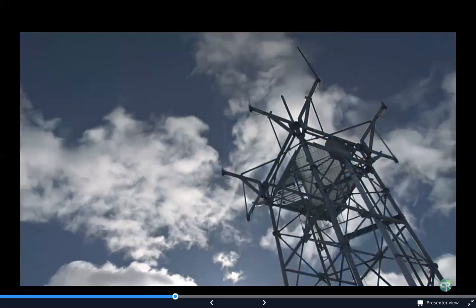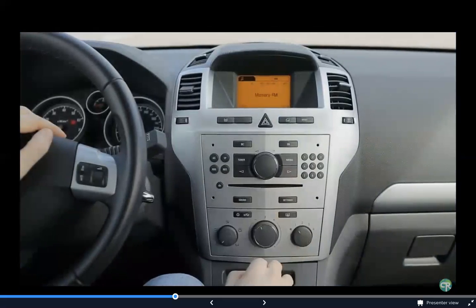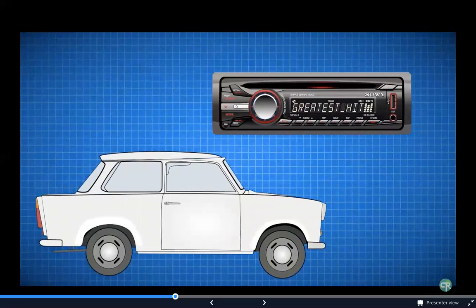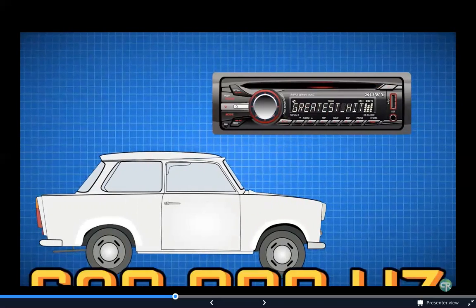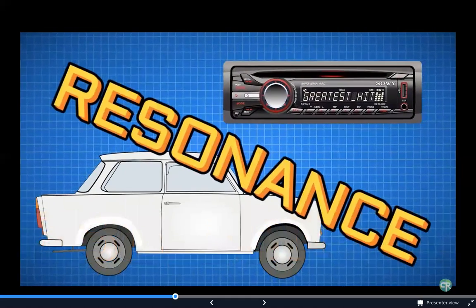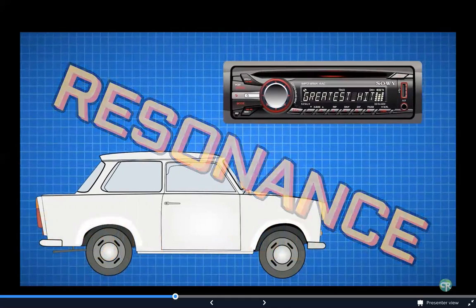Then the signal is amplified up to 50,000 watts for larger AM radio stations and then sent into space utilizing the antenna. Your car's radio picks up that signal, utilizing its own antenna. This can be as simple as a wire or a metal stick. In conjunction with the tuner on your radio tuning to the specific frequency, the tuner starts resonating at 680 kilohertz.